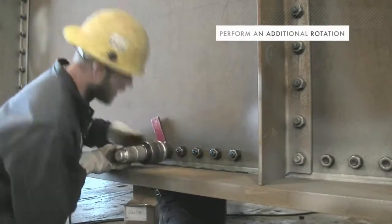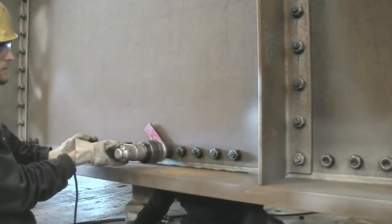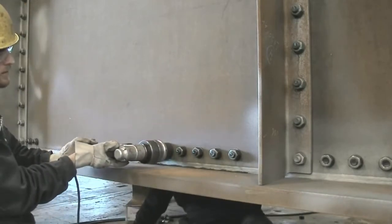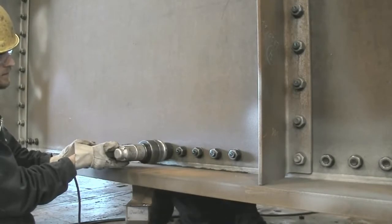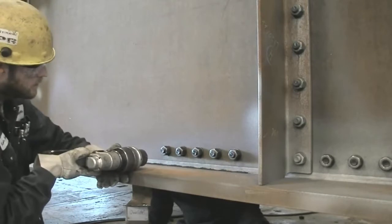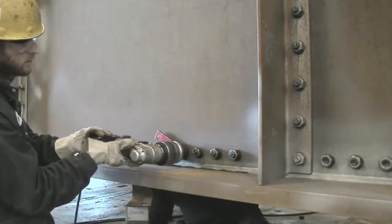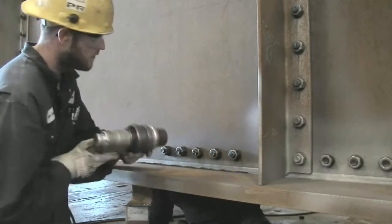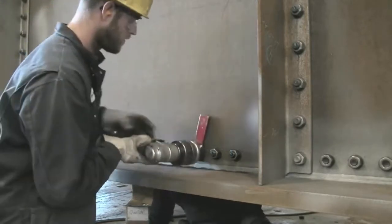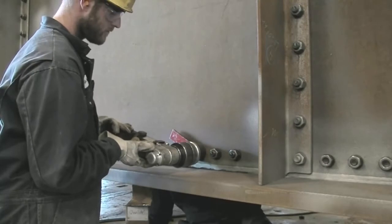And that wrench he's using is really just a really powerful wrench. You can see, there you go. That's basically it. If you notice, he's got this red guide on there that's helping him line up how much that needs to turn. And it's really just a lookup. You go to the RCSC spec and say, all right, here's my bolt diameter, group A or group B. I need to turn it an extra third of a turn or half of a turn. That's basically all there is to it.